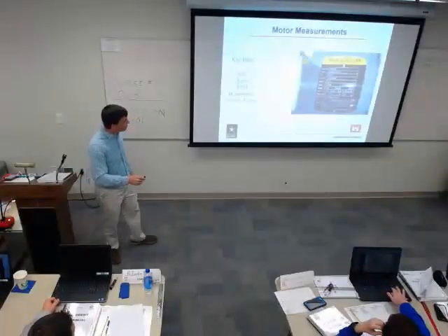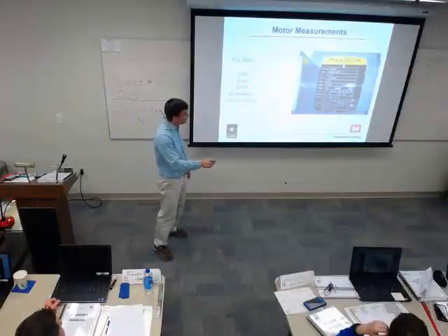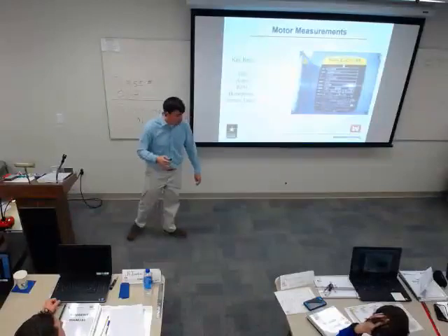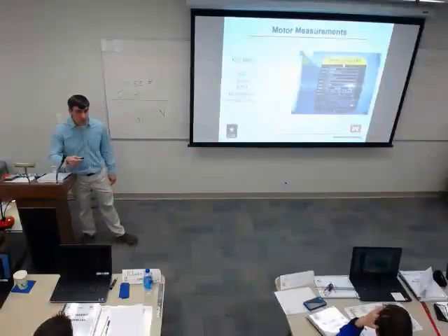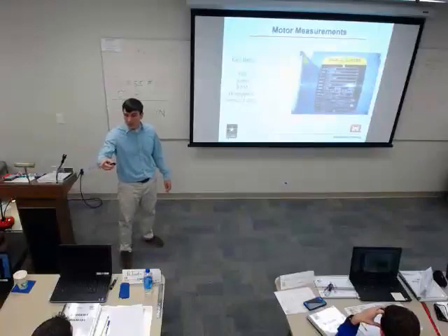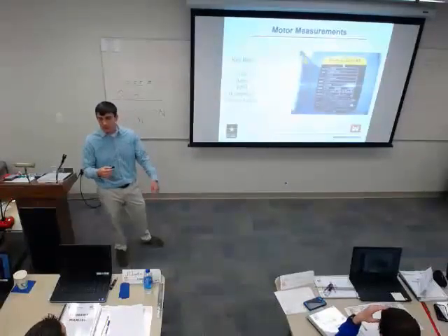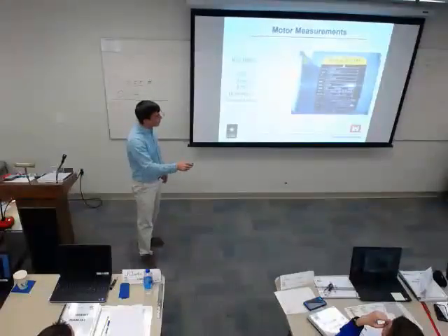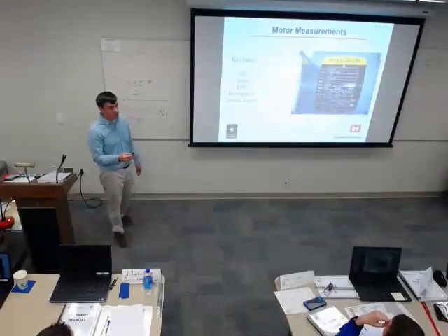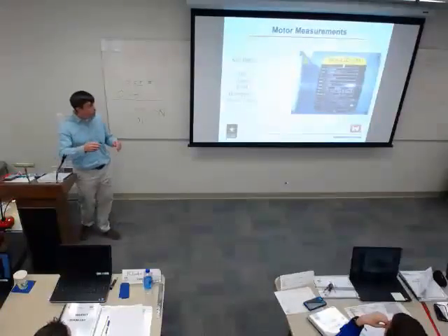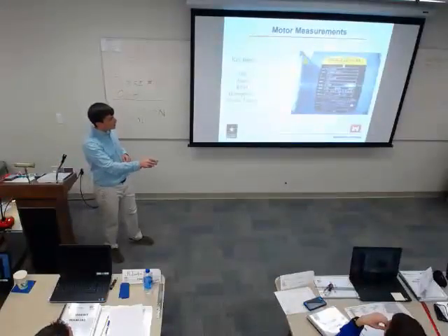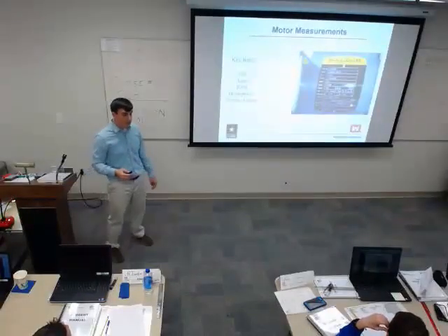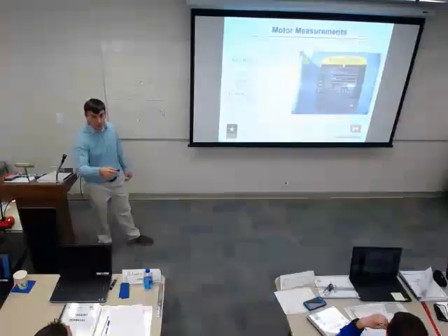And an important thing to talk about: I mentioned that you can't exceed this number. Every motor has what's called a service factor. You've probably heard your TAB contractor say, we'll just speed it up a little bit, we'll just be in the service factor a little bit. It'll be all right. No, never. Contractors are going to want to just speed something up and run it in the service factor. And the service factor is a number that, according to the manufacturer, means this motor can run up to 25% higher than its full load amps and not die. But it can't do it forever.